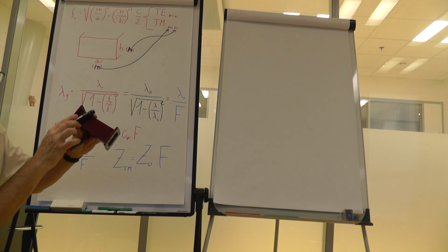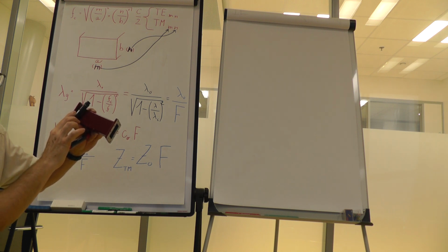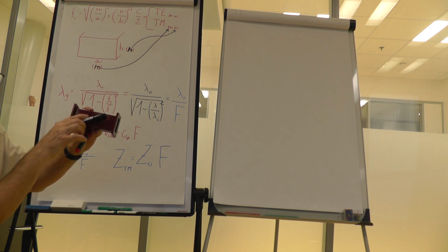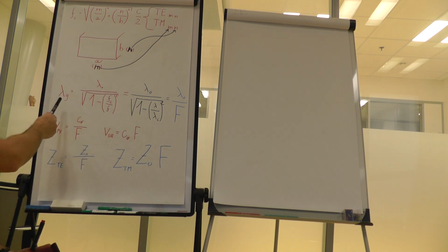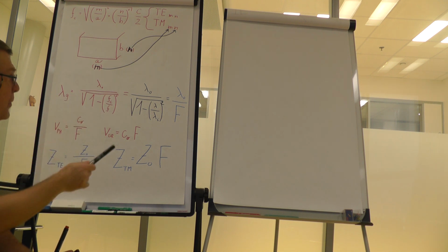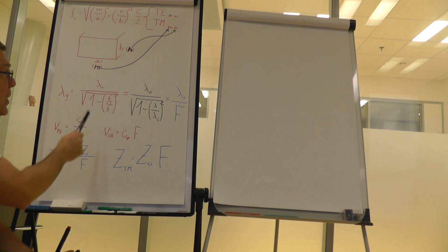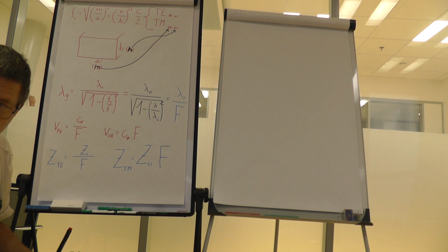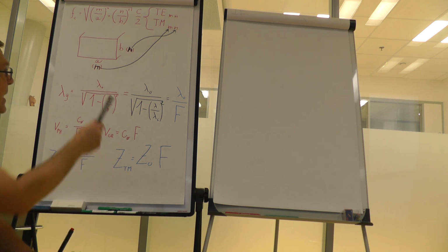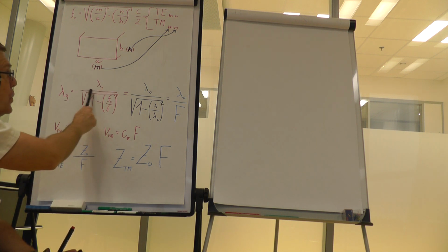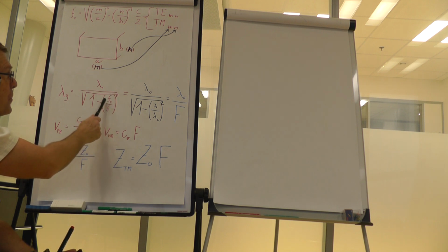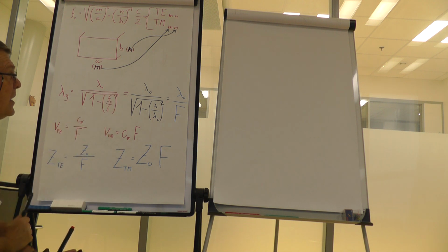Depending on frequency, it's quite perpendicular at the beginning. At critical frequency, it's quite tilted at higher frequencies. And this is expressed in this equation. So at any frequency f, if we have a waveguide with a critical frequency fc, we can calculate the wavelength in this waveguide as the wavelength in free space, lambda 0, divided by a factor which is the square root of 1 minus f critical divided by the current frequency, and that ratio is raised to the second power.